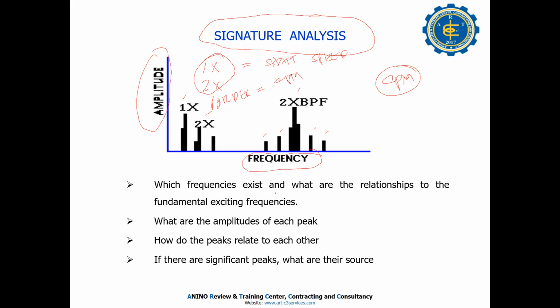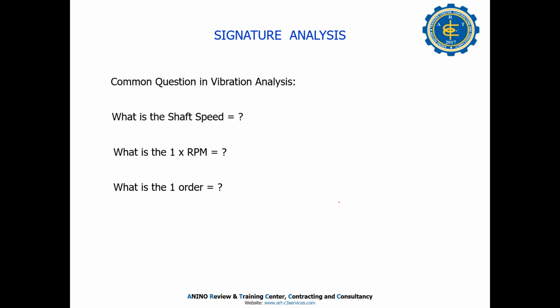Which frequencies exist and what is their relationship to the fundamental exciting frequencies? What are the amplitudes of the peaks? How do the peaks relate to each other? Are there any significant peaks, and what is their source? We can find that in the future slides, in signature analysis.